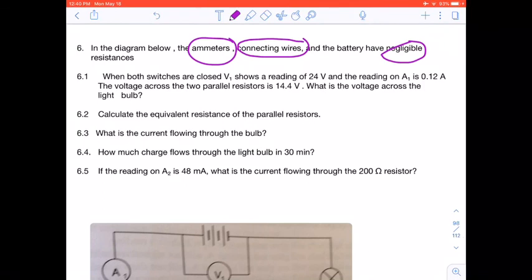Because remember, an ammeter must have a very, very small resistance, because otherwise the current going through the ammeter will cause a potential drop. So what's being measured is not the drop across a particular component, because there's a voltage dropped in the instrument as well.